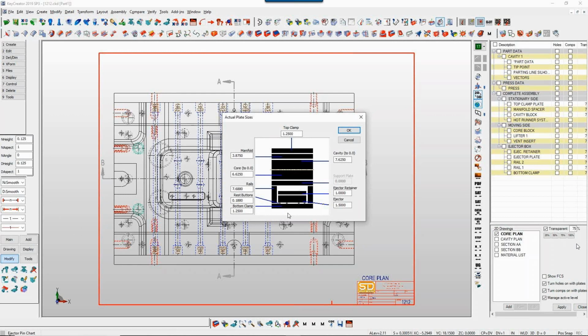What your shop would do is backfeed you when all the plates come in from Blanchard grinding and stuff. They're going to mic them. That's standard, right? When it comes in the shop, they check sizes and make sure they're what was ordered. When they do that, they record those values. Then those values go up to your engineering department, and you can type those values in and say, well, the rails actually came in at this size.